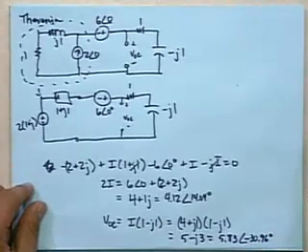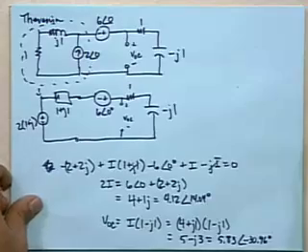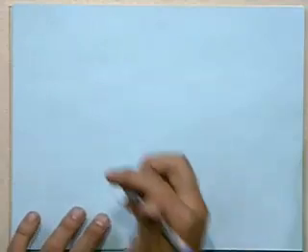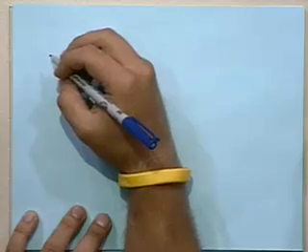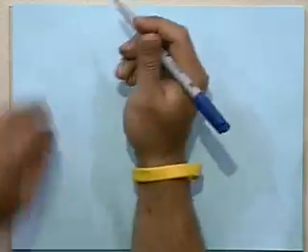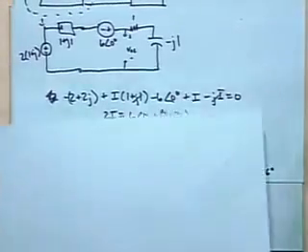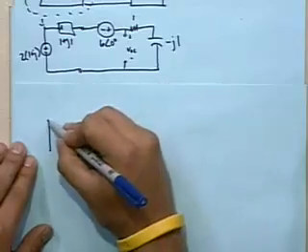Now we need to calculate the Thevenin impedance, since this is just a circuit with independent sources in it. So let's zero out all of the appropriate sources. What you should see, especially if we continue to look at it from the point of view of this transformed version of the circuit, is that this voltage source gets shorted.